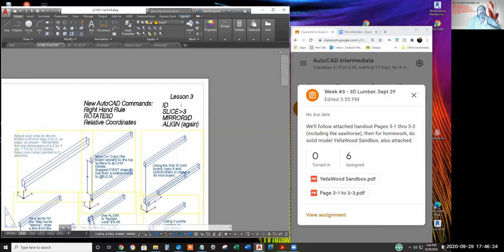As Dan pointed out, if you stop and think for two seconds, you can select a shortcut rather than picking 3 points on the slicing plane. Mirror 3D is similar to slice. I like to specify 3 points for the mirroring plane, but there are shortcuts if you take two seconds to select the proper one.